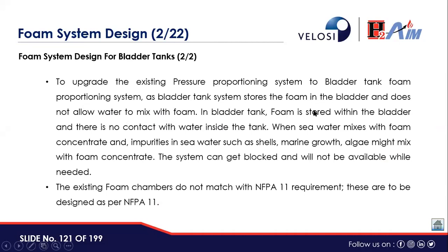In a bladder tank, foam is stored within the bladder and there is no contact with water inside the tank. When seawater mixes with foam concentrate, impurities in seawater such as shells, marine growths, and algae might mix with the foam concentrate as well. The system can get blocked and will not be available when needed. The existing foam chambers do not match with NFPA 11 requirements. These are to be designed as per NFPA 11.